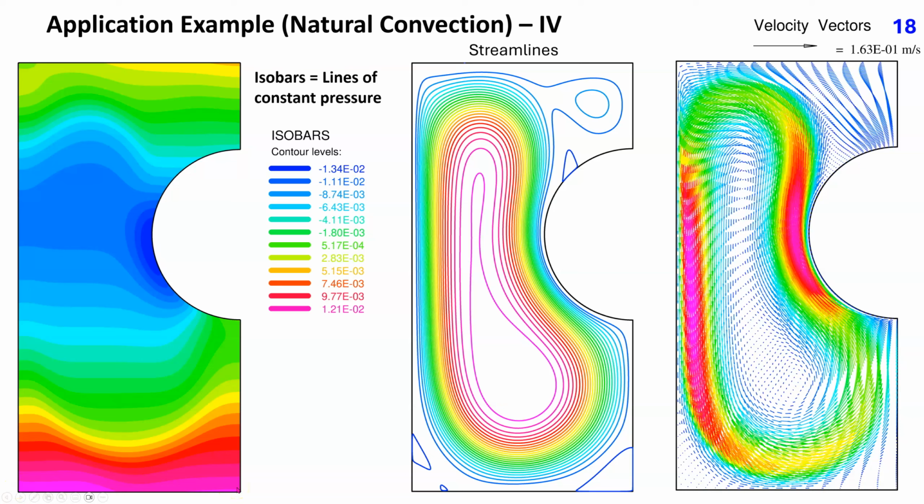Note that isobars are sometimes orthogonal to walls and sometimes not. Zero gradient condition applies only to the pressure correction at boundaries where the velocity is prescribed. Here, zero velocity at a wall, no slip condition. When the converged solution is obtained, pressure correction is zero everywhere, but the gradient of pressure in the direction normal to wall boundaries may be non-zero depending on local conditions.